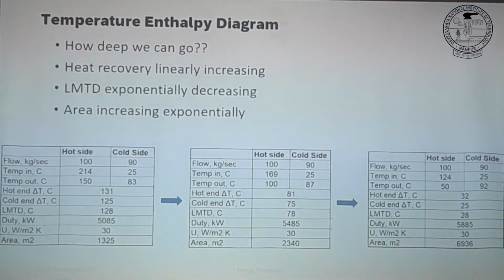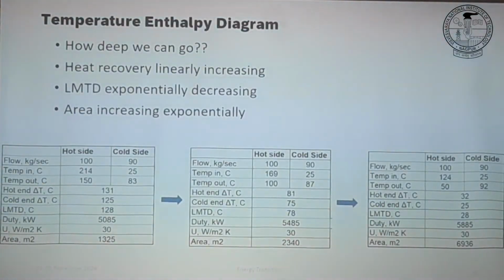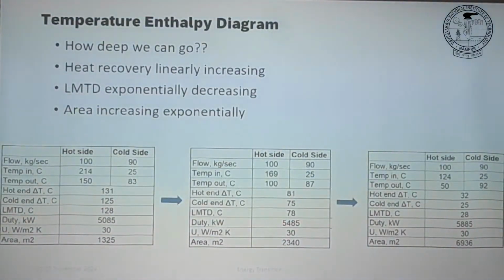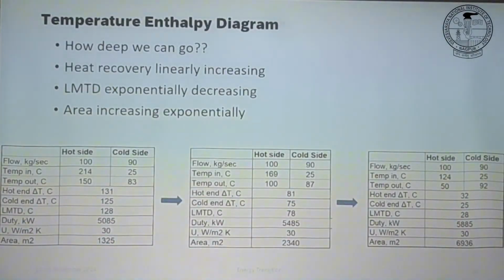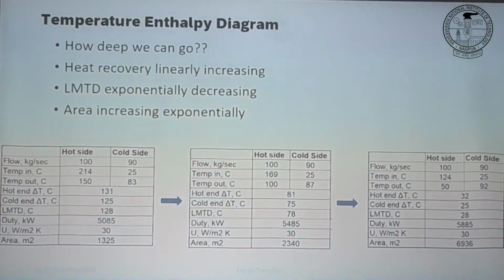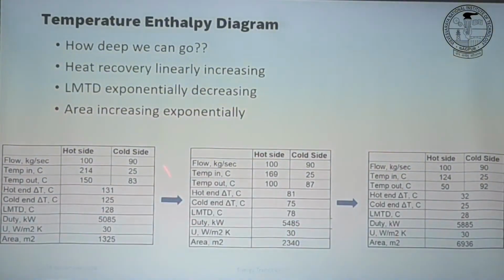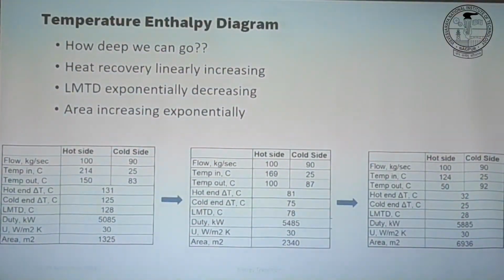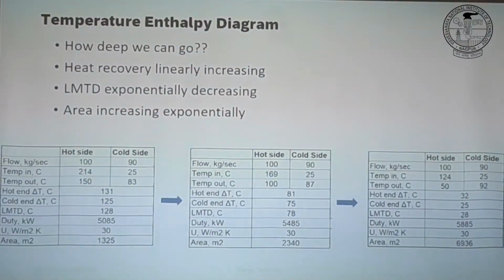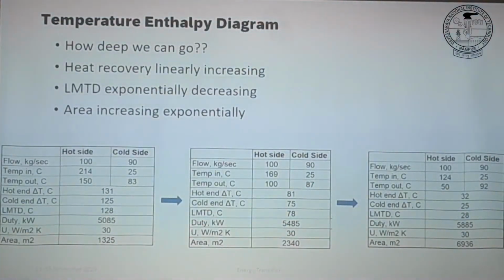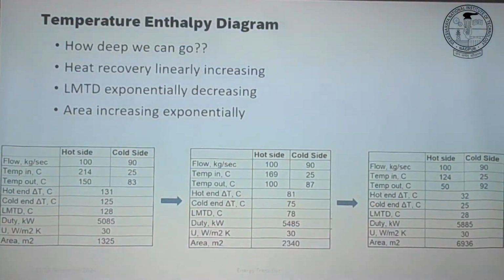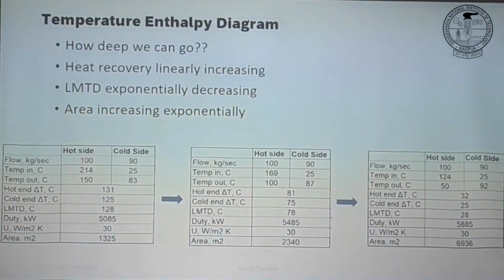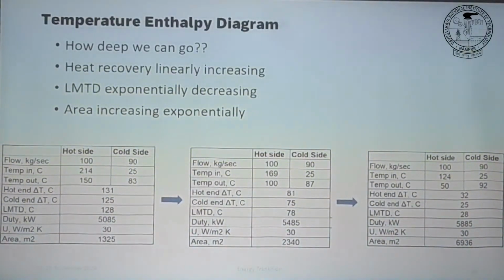If you have water on both sides, maybe 10, 15, or even 10 is okay. So there is an optimum, because you cannot plot this curve all the time to see how it's going up, what's my total cost. So you work with these design rules. You remember that, okay, for such I take 50, for water I take 10. There are some special designs of heat exchangers where even a temperature difference LMTD of 3 is possible.